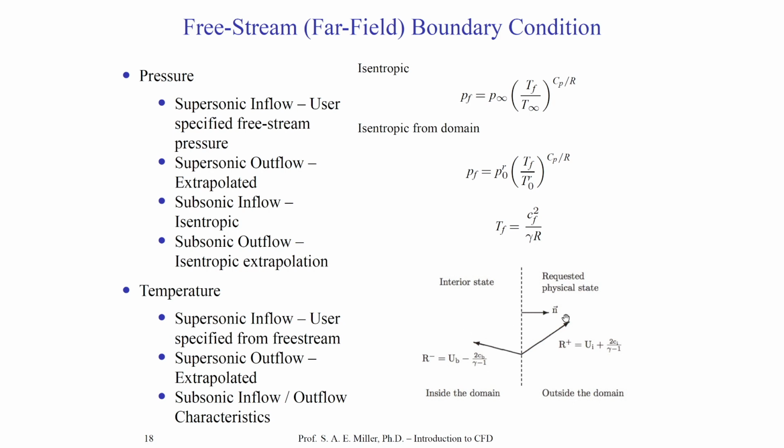You can flip these values to find inlet conditions. Take a second to see these. You can imagine how they're derived using the method of characteristics using the flow equations of motion. This is usually done in a graduate computational fluid dynamics class. We would also be specifying temperature, and for supersonic inflows, of course, the static temperature would be specified.